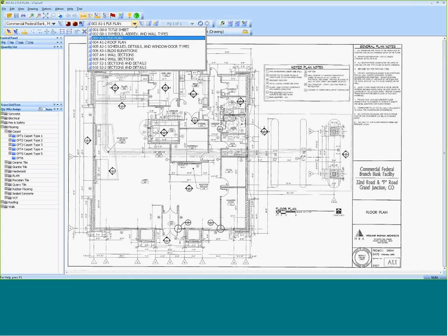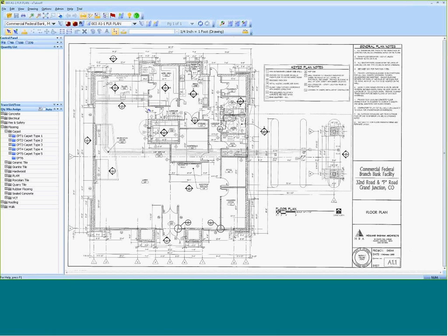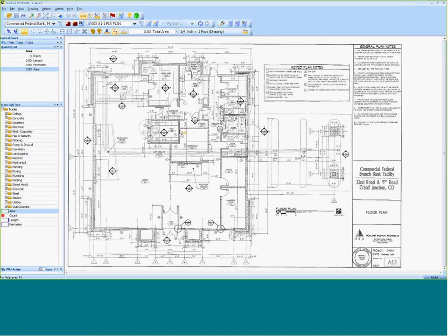There's a little tiny project that I use for demonstrations. But if you want to take a basic measurement, you could use just a simple area, for example. So I could double-click here, just an area measurement. All I have to do is point and click, and I go around here. Oops, I messed up. So backspace, backspace. So I can fix things pretty easy and keep measuring.